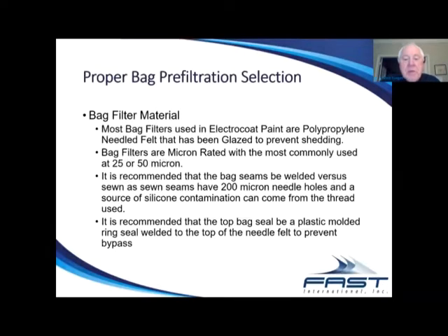We also recommend that the bags have a top sealed molded ring and not just a snap-in ring or a steel ring that's sewn into the top of the bag. This will help prevent bypass of the paint around the ring. Recently I was at a facility where the bags had metal rings in them, and when you put the bag into the bag housing, the rings broke. They broke at the weld.